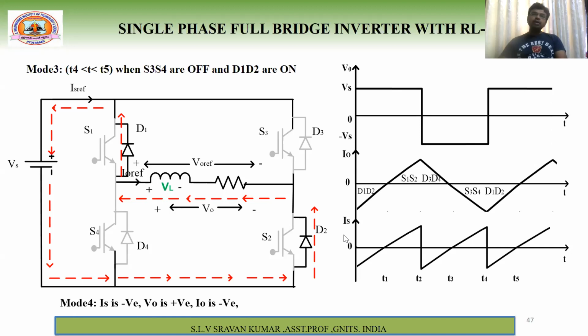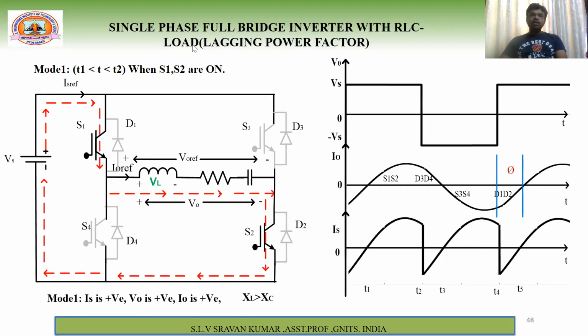Okay. So this is about your single phase full bridge inverter with RL load, right? Now coming to the next one, single phase full bridge inverter with RLC load, lagging power factor. Lagging power factor means what happens? The inductive effect is more than the capacitive effect. That is a very important point we have to identify here.